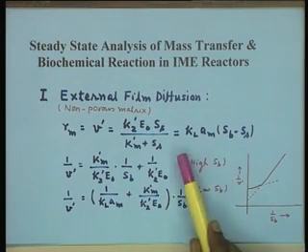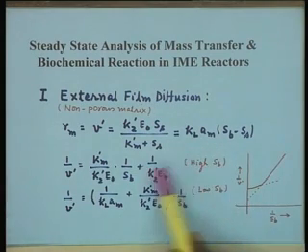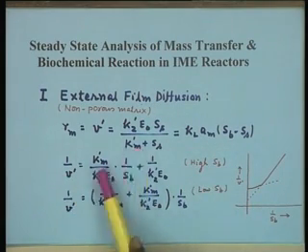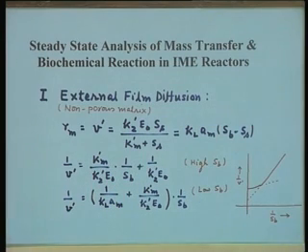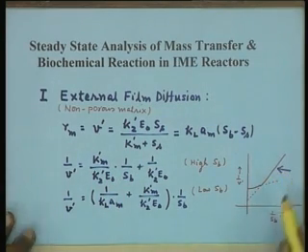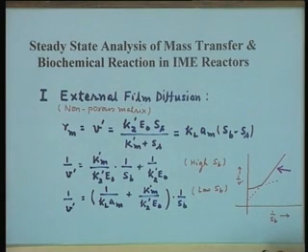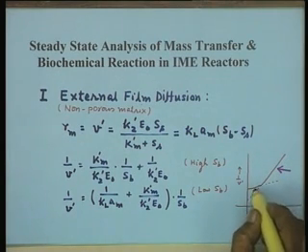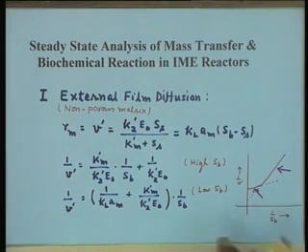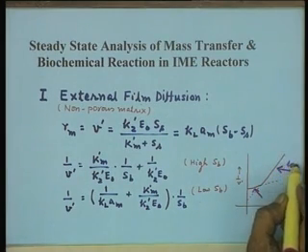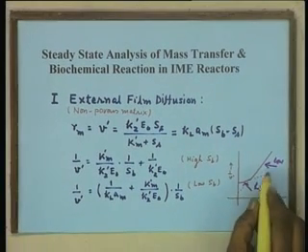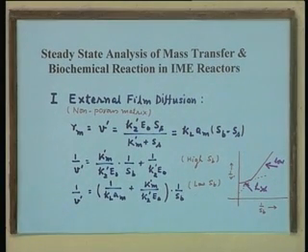One, under high substrate concentration we get a Lineweaver profile which is analogous to ordinary soluble enzyme kinetics. And in the case of low substrate concentration, you get a difference in slope, and the measurement of slope at two distinct stages of Lineweaver plot gives you an estimate of the value of mass transfer coefficient due to film diffusion.